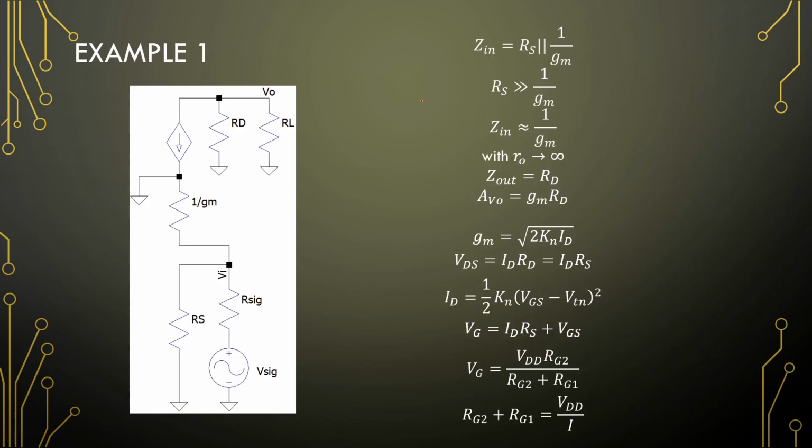First we can write down everything we know about this amplifier. I've taken out the output resistor since we don't have any information about that, and our small signal simplified to something looking like this. Now, our starting point would be 1 over the transconductance and our input impedance. With our transconductance and choosing a drain resistor, we have our gain.